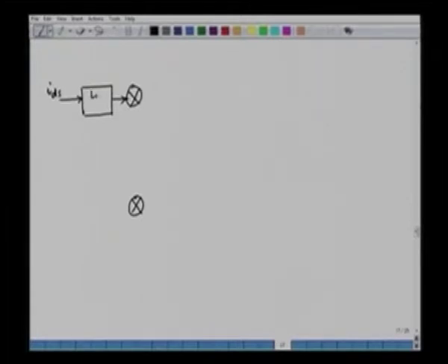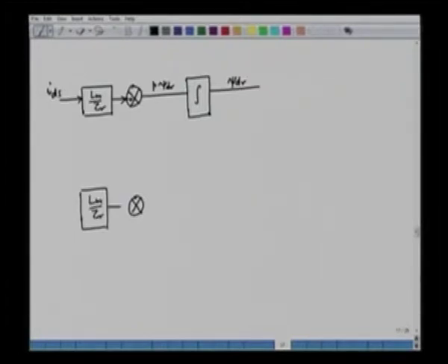We multiply here Lm by tau r, and then the output is P psi dr, and we can use an integrator here, and what we obtain is psi dr. And similarly, for the q axis, we have Lm by tau r, and then we have IQS here, and we integrate this.